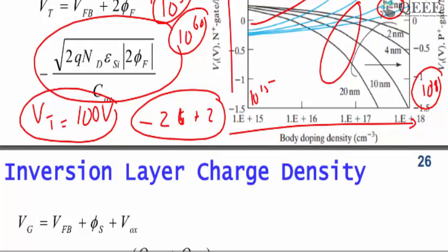But we will see when it comes to a transistor, a current can flow, because here there is no lateral current in a MOS capacitor, since it's all M, O and S. If there is a current, it has to flow between the gate and the semiconductor, but because the oxide is very thick, that is preventing it. So there is no subthreshold current in a MOS capacitor, but there can be subthreshold current in a transistor.